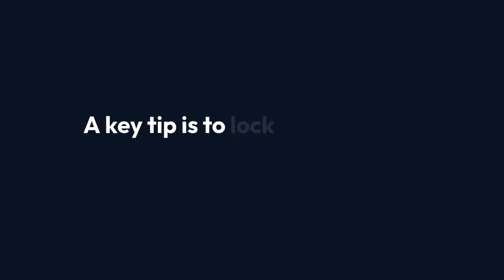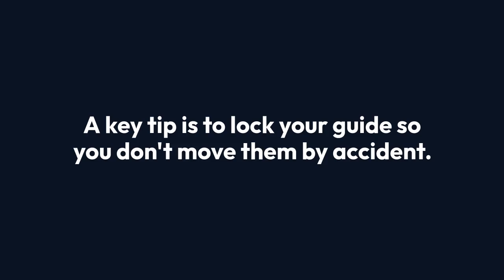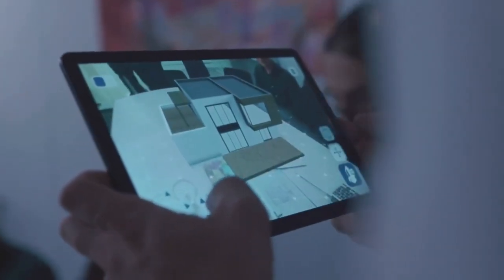A key tip is to lock your guides so you don't move them by accident. Just go to the View menu, then Guides, and select Lock Guides. This will save you a lot of frustration.